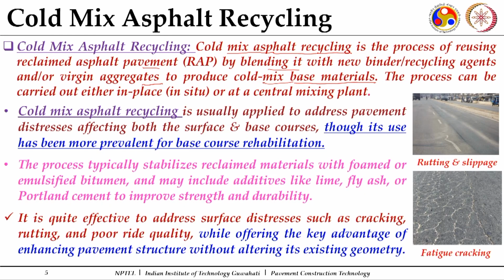That means after the construction of the base course, one definitely needs to go with an overlay of a wearing course, a bituminous overlay over it. The process can be carried out either in place, in situ, which is cold in place recycling and full depth reclamation, or at a central mixing plant, which is cold in plant recycling.